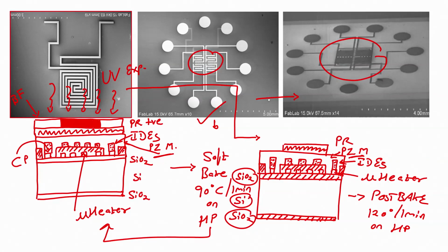That is why we have used photoresist, and we have patterned the photoresist in a way that it will protect the piezoresistive material below it only in the wanted area. In the unwanted area, if I put this chip in a piezoresistive etchant, whatever the material we are using, what will happen? The piezoresistive material will get etched, right. So, you see this area it got etched, rest of the area it got etched, correct, right, easy.